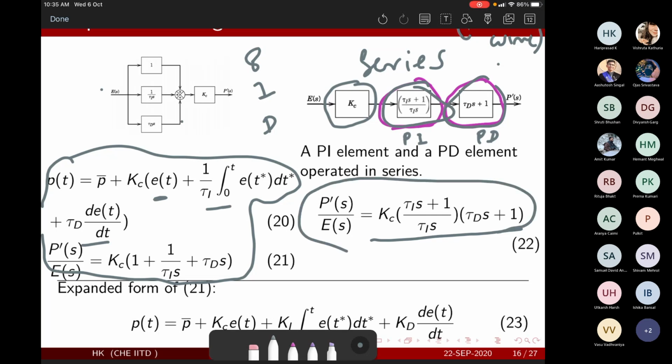So the proportional fraction would be doubly acted on the system. So this is the overall series form of the PID controller. But again, the good thing is that you have a lesser number of tappings. Here you have multiple splitters and multiple combiners, while in the other form, you have a limited number of taps, but your P value would be doubly acted because it's a combination of PI and PD. So if you factor in, the effect of P is counted 2 times.